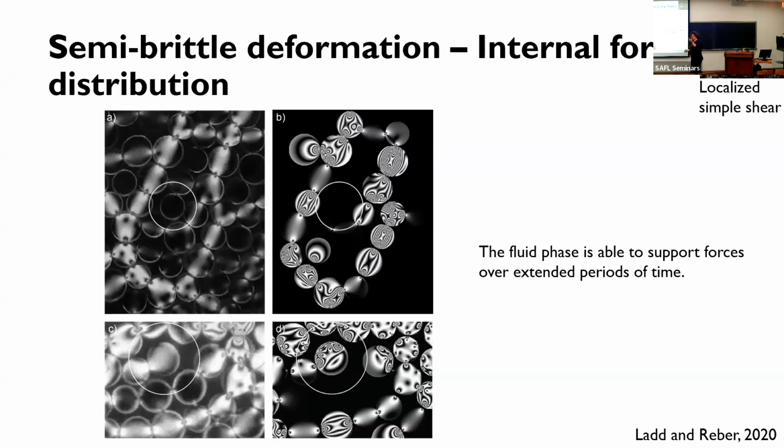The light is coming from compression. All these beads are lying on a table. Light is coming through the beads in a polariscope. So it's polarized light. Everything that remains dark is unstressed, and everything that is lighting up is under stress. Yes, exactly.